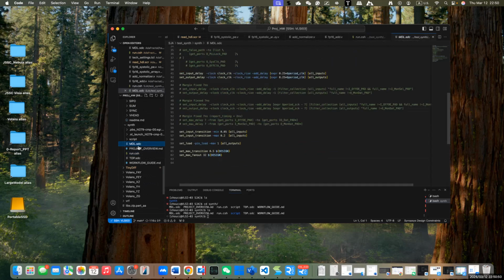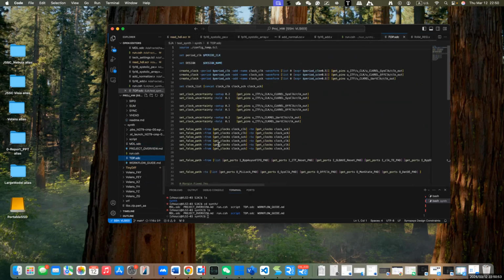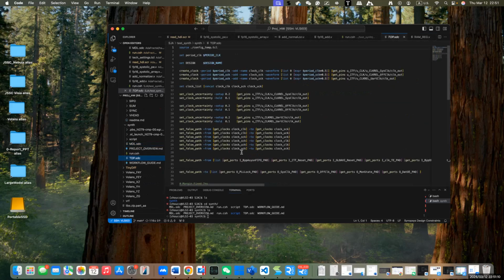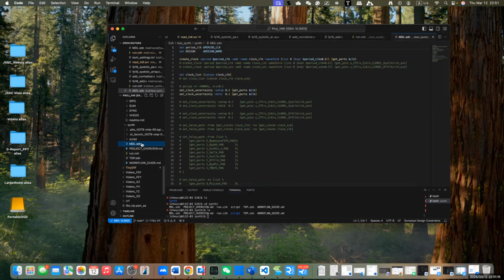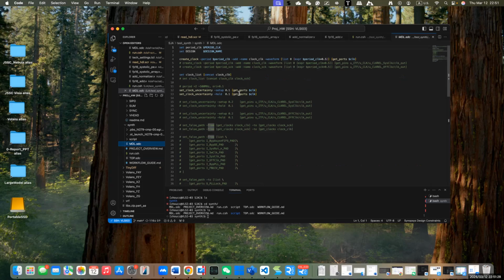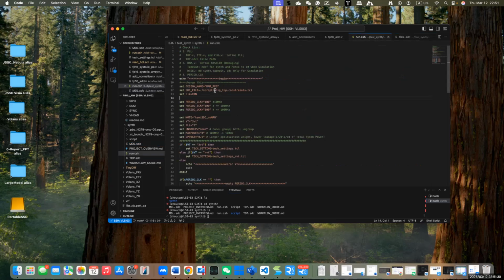This file is the edited STC file. This is the second. What's the difference between the two files? Usually, if you synthesize the sample module, you use this file. If you want to synthesize for the whole chip, use the whole STC. You can see that this file is very simple. In this file, I have three clocks. So for this simple module, you use this file.